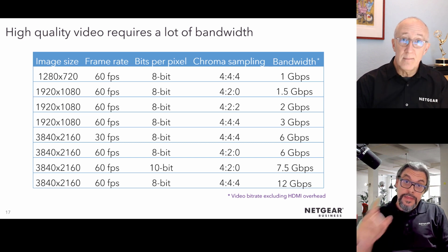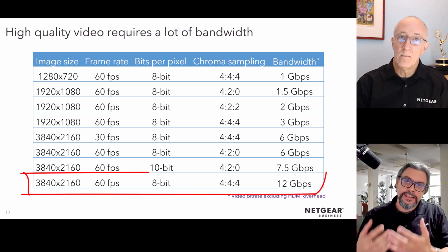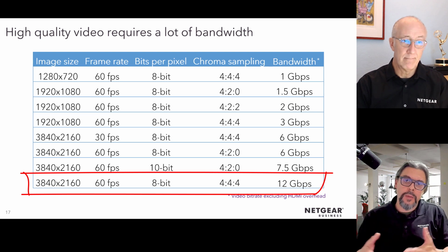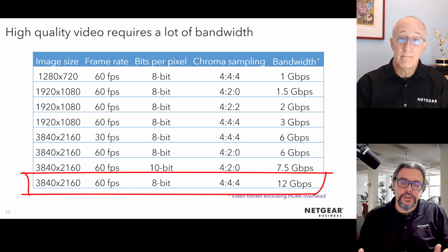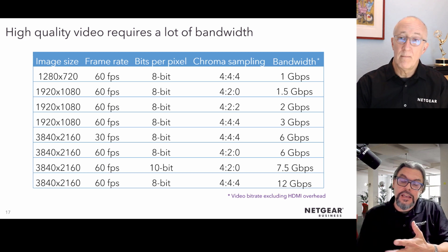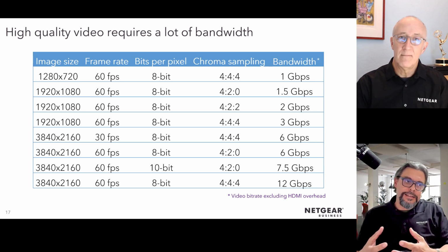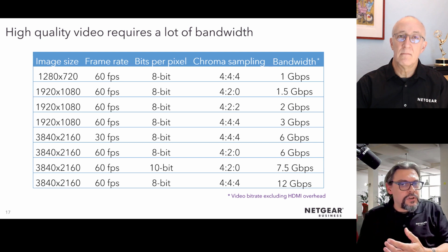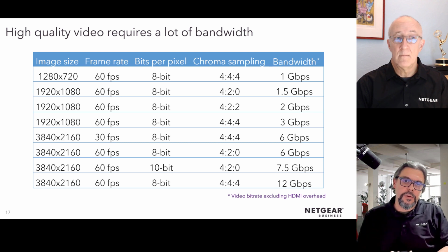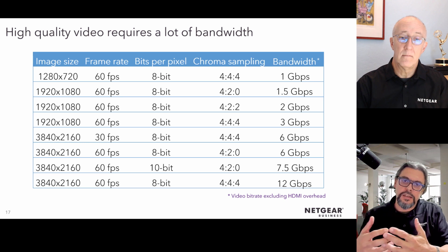And that's where now you can understand that when you want to squeeze 4K 60, 4:4:4, the last row, into a 1G pipe, you need a hell of a compression effort, right? So a lot of compute. So compression means some kind of delay because you don't have a super calculator to do it. You have an encoder, and it will take some time. So that's why you got to give up a little bit on latency when you want to compress that much, and maybe also some quality effect, because 12 gig to 1 gig, it's a lot.